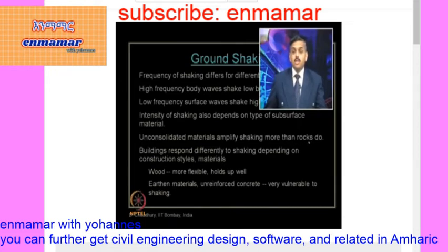So rock generally doesn't amplify the input ground or base level ground shaking, but unconsolidated material, the soft soil material, will amplify or increase the seismic acceleration when it passes through this unconsolidated material. So that's why we have to be very careful about soft or unconsolidated material, if anything exists below our site of concern where we are going to construct any new structure.